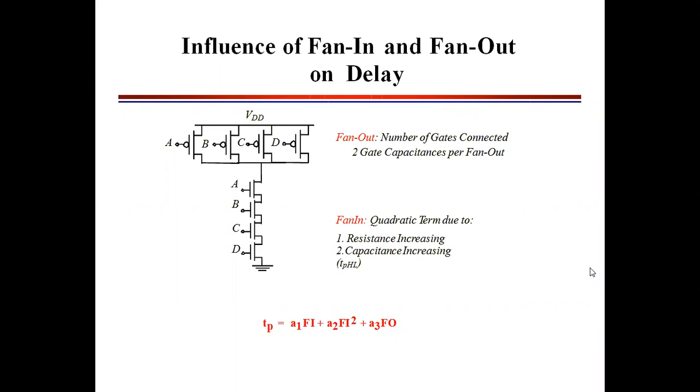It is specifically mentioned by the manufacturer. Whatever NAND gate IC you are using, the manufacturer must mention its fan in and fan out value, because you cannot connect an infinite number of inputs to a particular device. It is not allowed. There is a restriction, there is a rule. You have to study its fan in and fan out value, and only then can you decide how many inputs that device can accommodate. That is your fan in.